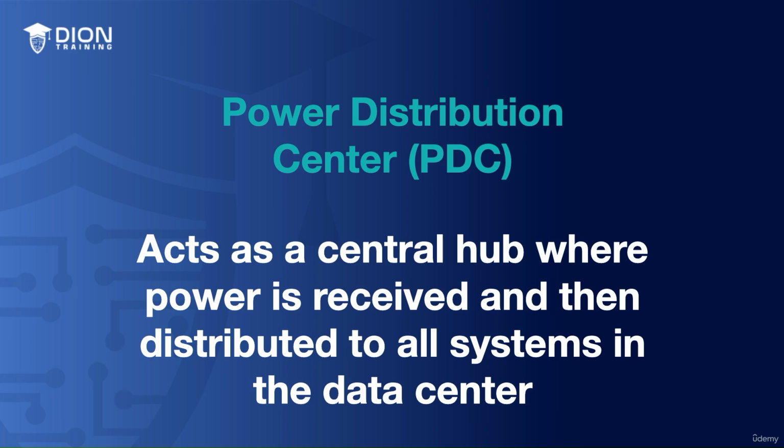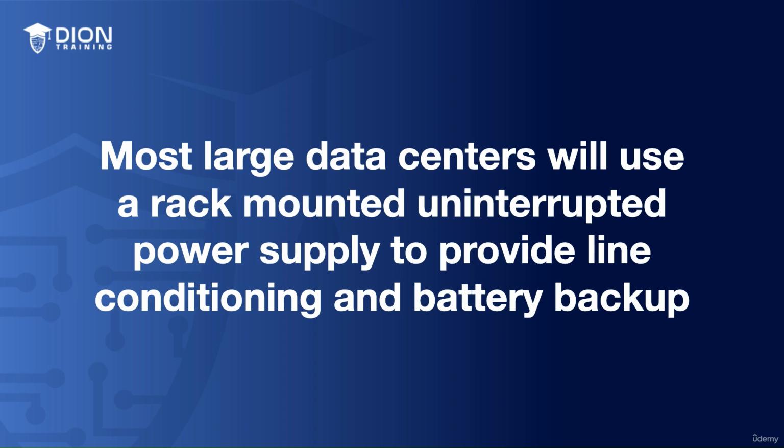Now, in order to ensure you have solid power to all of your devices, you're going to need to build your data center with multiple layers of protections and redundancies. Your exact setup is going to be defined by your use case and your budgetary limitations, but most large data centers will use rack-mounted uninterruptible power supplies to be able to provide line conditioning and battery backup functionality to all the servers contained within a given server rack.